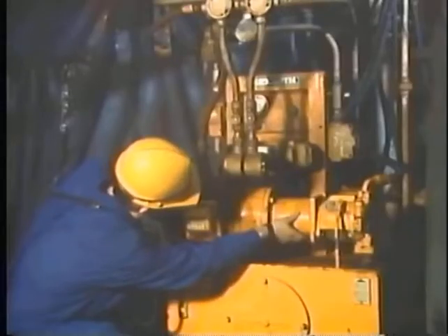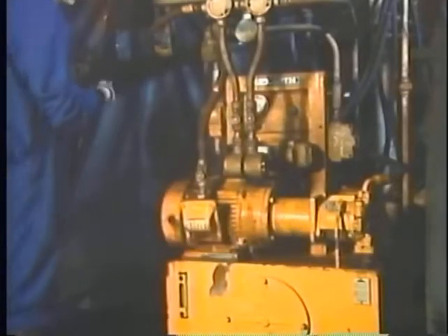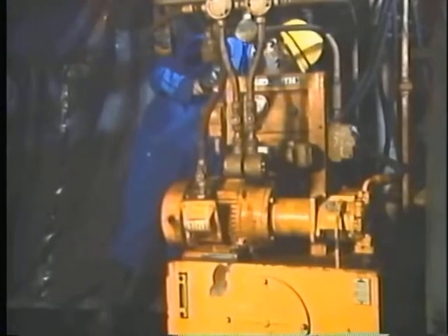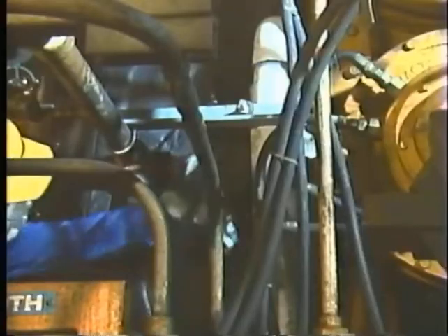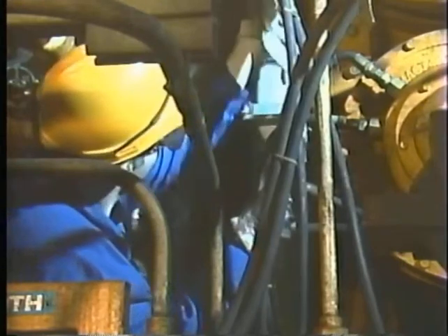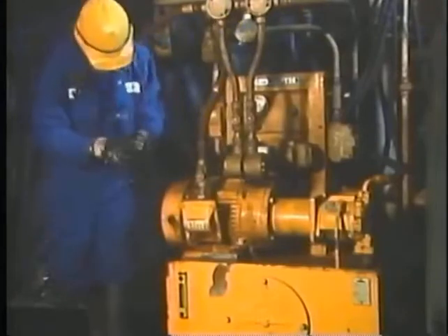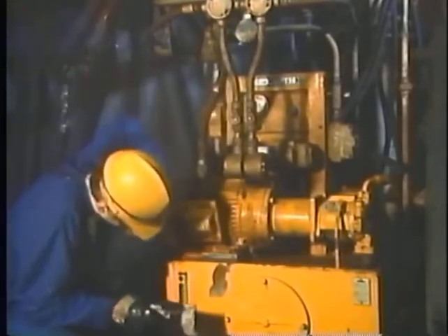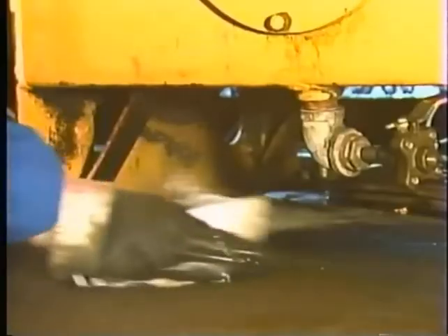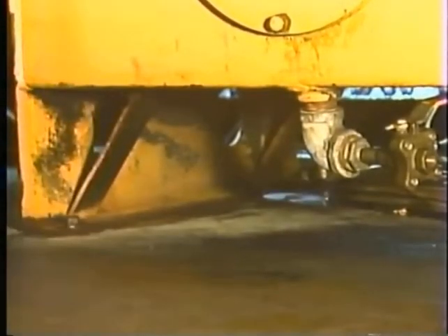In this part of the program, we'll look at some typical checks that operators should make on hydraulic systems to keep them working the way they should. One part of an operator's job in checking any system involves looking for obvious signs of damage. In this case, looking over the fluid lines for leaks, especially around connections, is also important. If a leak is found, any accumulation of fluid on the floor is slippery and should be cleaned up to avoid causing falls. Then, the appropriate action should be taken to have the leak repaired.